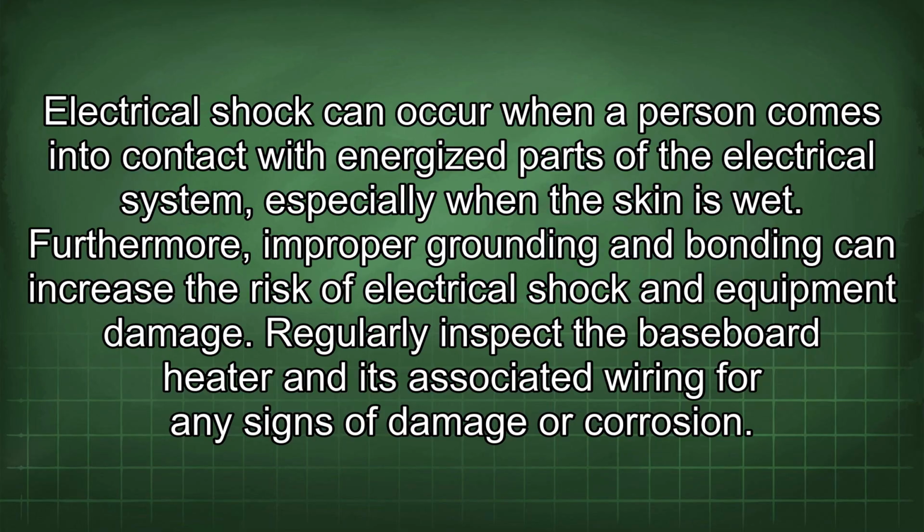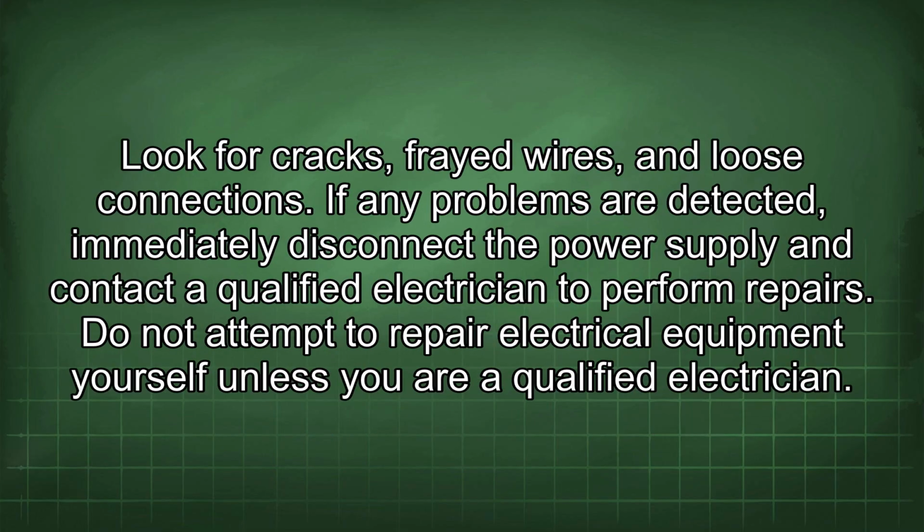Regularly inspect the baseboard heater and its associated wiring for any signs of damage or corrosion. Look for cracks, frayed wires, and loose connections. If any problems are detected, immediately disconnect the power supply and contact a qualified electrician to perform repairs. Do not attempt to repair electrical equipment yourself unless you are a qualified electrician.